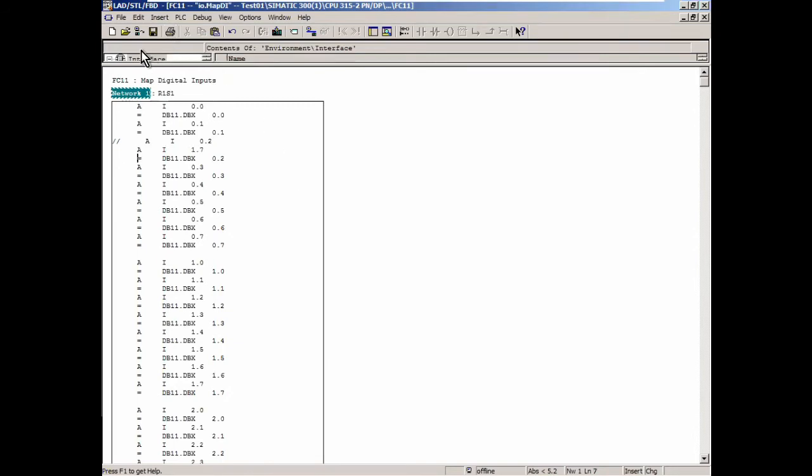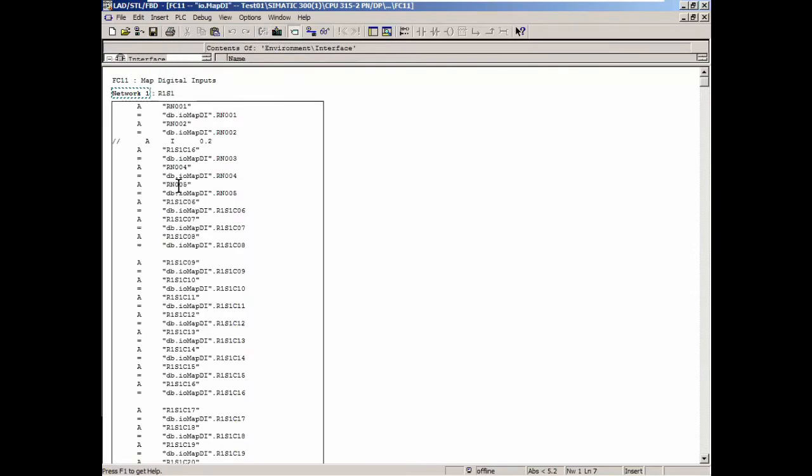And then if I save and copy it and download it, I'll put the symbols back on, and you can see that one is spare. We could then change the symbol to say this is the old one, this is now bridged or something. But the actual program which uses this run feedback, we don't have to change anything because we've changed the IO mapping here. So we don't have to search for this input anywhere else in the program. It is done once.